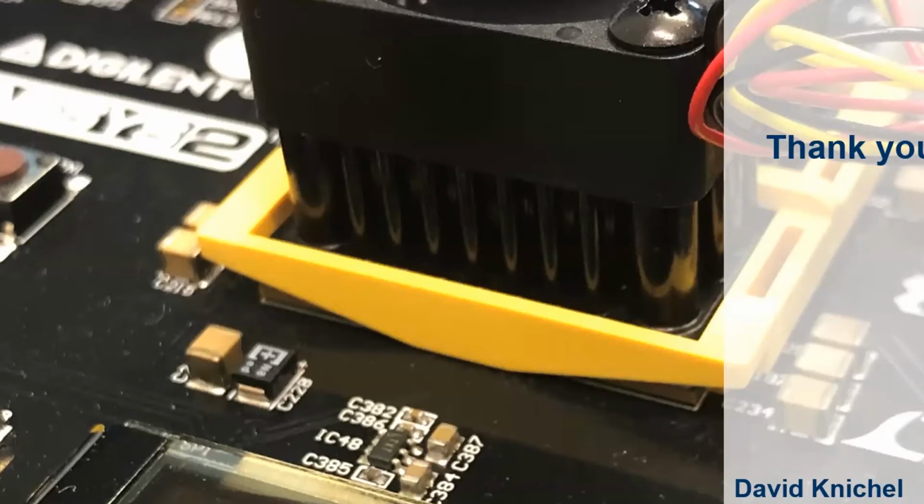You mentioned in the beginning of the presentation that you can efficiently compute the distribution of the wires. Is this claim conditioned on some sort of statistical independence on inputs, or was this just a general claim? I mean, these are OBDDs, so efficiency-wise they heavily depend on the input dependencies. The complexity for this check gets higher if you have more input dependency, meaning that you have more multiplications in your Boolean functions and things like that. Then computing the distribution will get harder.